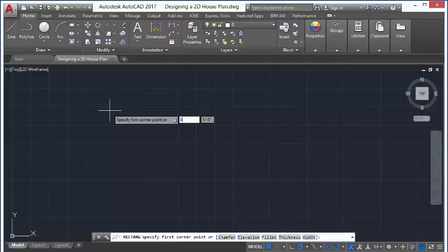In the next input, I may use the tab key so that you can have confidence that the two keys have the same function in AutoCAD. In AutoCAD, there is no one or two way of doing things, there are more than one or two ways of doing things. Now press your comma key. AutoCAD locks the 0. Any input you now enter goes straight to the y-axis. In the y-axis, we need another coordinate of 0.